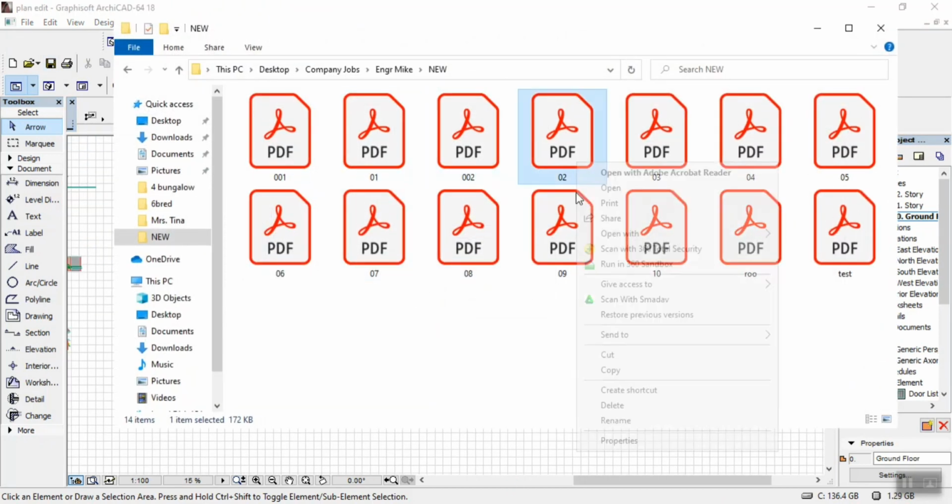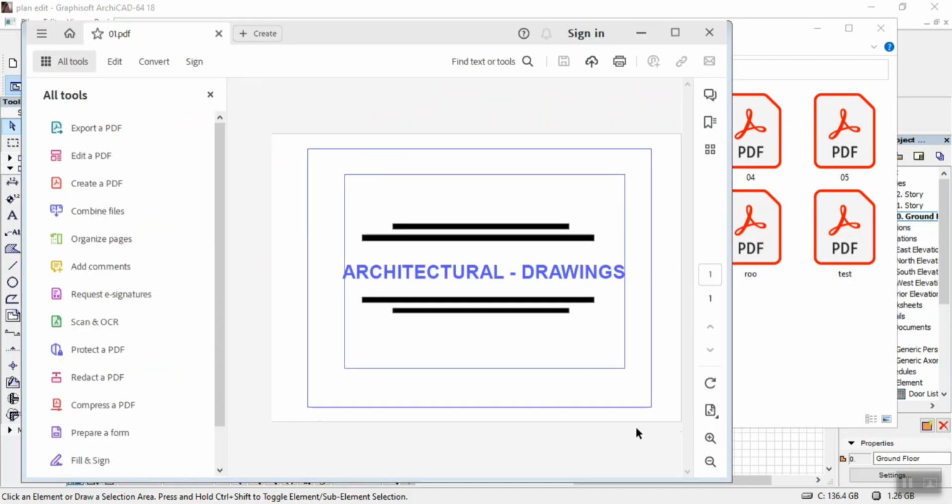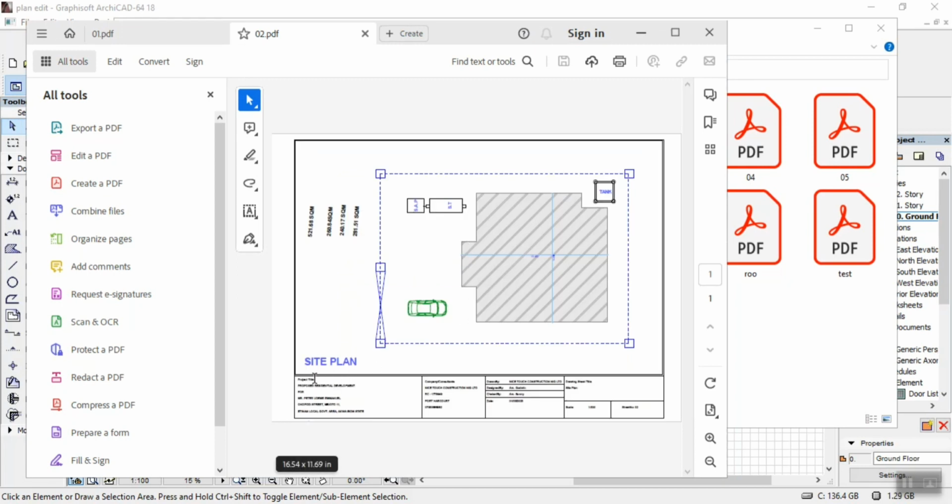So let's check for the next. What's the next? 002. Let's see what is 002. 002 is known as site plan. The real name is site analysis, site plan. This is where you have to work out all the dimensions, the square meter of the land, whatsoever is left after your building, the total square meter of the land, the total square meter of your building, the soakaway, the safety tanks or placements, the place for the water, everything. This is what it means by site analysis. So this is the area where you need to concentrate very much on. You don't need to skip any part of this place.